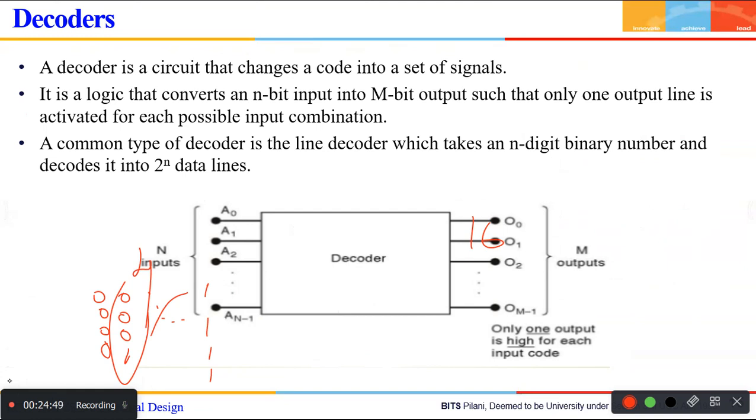That's what a decoder is, that's all. If you want to connect 8 LEDs, how many inputs are required as input to the decoder? 3. That's all. That's what a decoder is. Have you understood this now? Okay? This decoder has lots of applications in microprocessors.